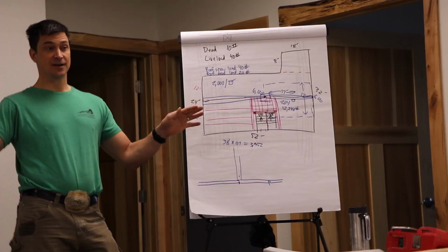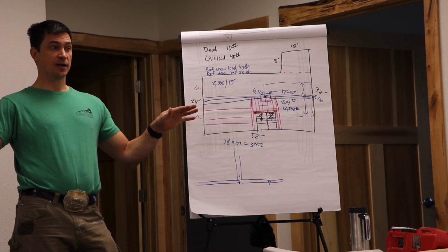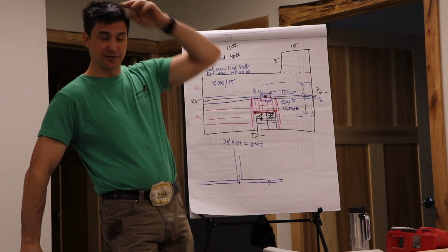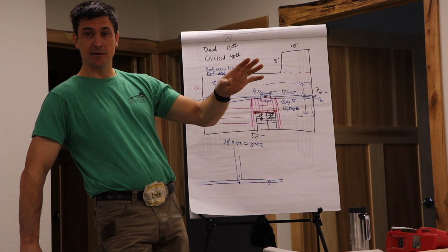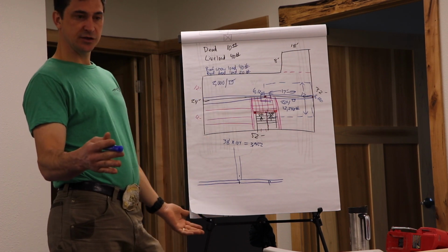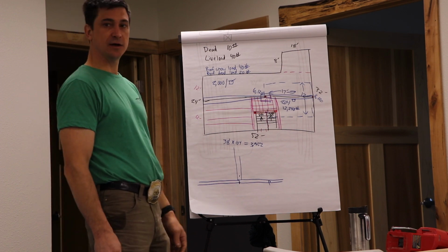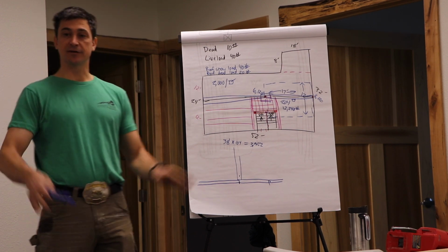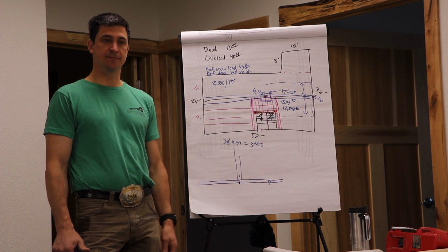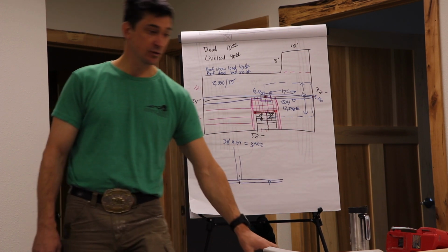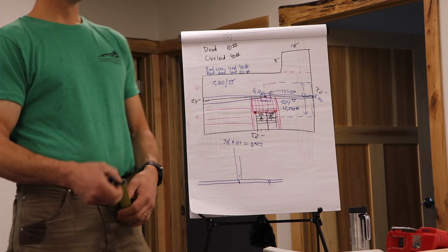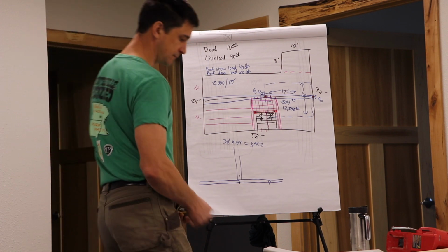It all depends upon where you want to put the X. That has every new guy out in the field scratching their head or laying it out wrong, and then you run your sheathing and it's like, dirty mutt, my sheathing won't hit that stud. Okay, just why am I making this mark this way? Where do we put the mark? 3/4 inch back. Okay, why? So that the line isn't covered.